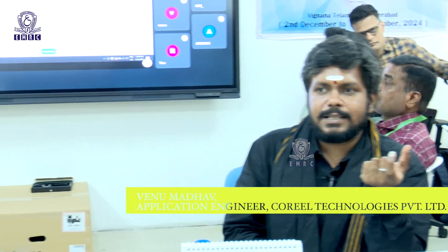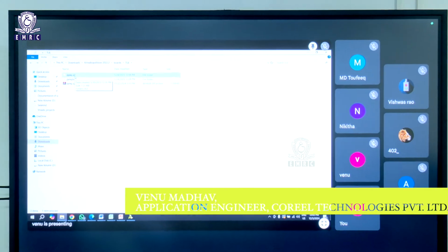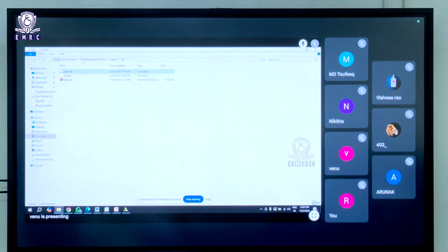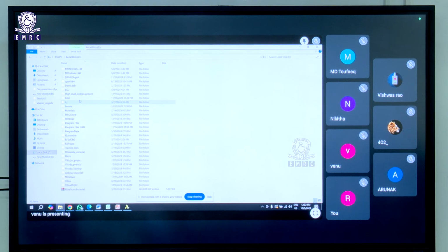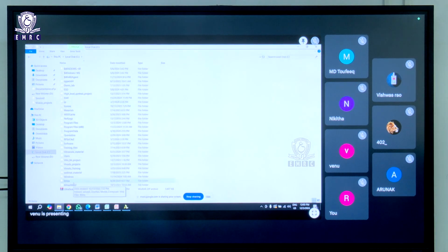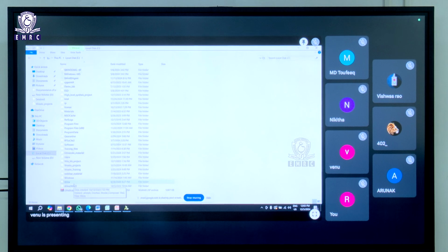So this is the board support package. These are also called board files. So where do we need to paste this so that the tool will pick it up? You can go to this particular path where you have installed Vivado, where you have installed Xilinx. Should mostly be in C drive under the folder called Xilinx. Inside Xilinx, you will be able to find Vivado.